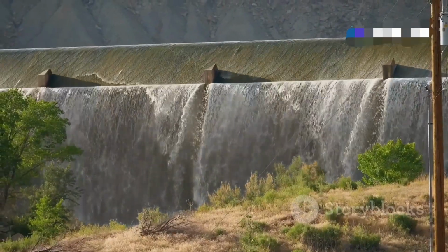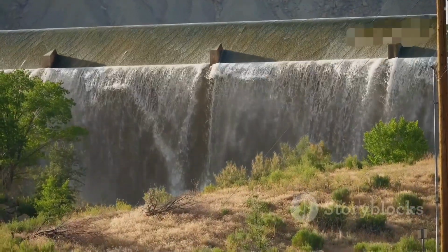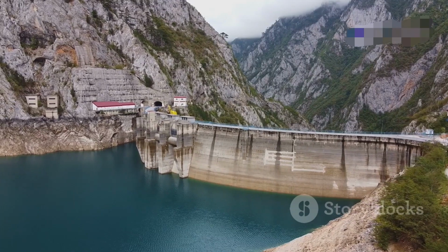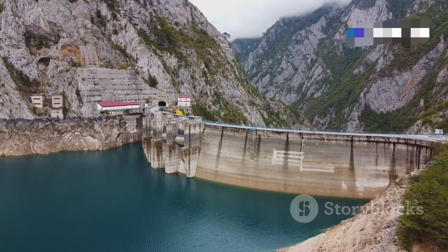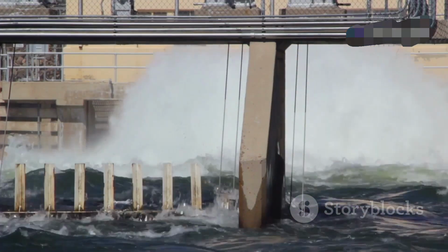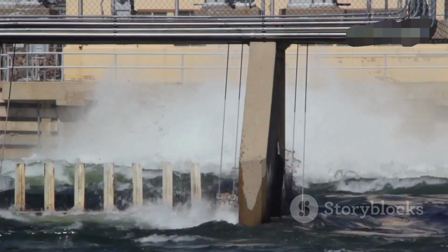Earthen dams, especially those made of easily erodible materials, can fail relatively quickly, sometimes within a few hours or even less. The height of the dam also matters. Taller dams with more water pressure may erode faster. The mechanism of failure is also important. For instance, an overtopping failure that rapidly erodes the downstream face might progress faster than some piping failures.